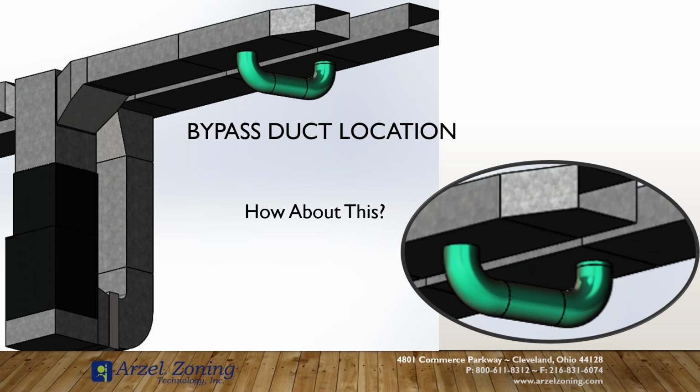Yes, it just causes a lot of performance issues when you do that, and more often than not, somebody calls me up and says that the furnace is constantly running on limit. It's because of where the bypass is installed, or it's because the bypass is oversized more often than not. So proper installation helps to maintain performance.